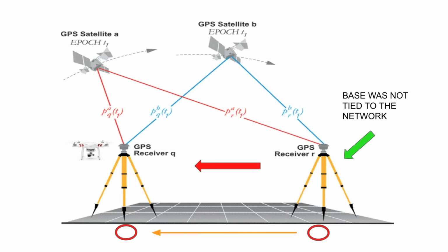The relative accuracy of the drone positions was excellent, but when we tried to tie it back to the ground control points, we had this bias, this offset problem. Once we figured it out, everything matched up very, very well, and that's what it should do. And that's really the beauty of RTK capable drones, or PPK capable drones, and also the beauty of photogrammetry, that they complement each other so well.